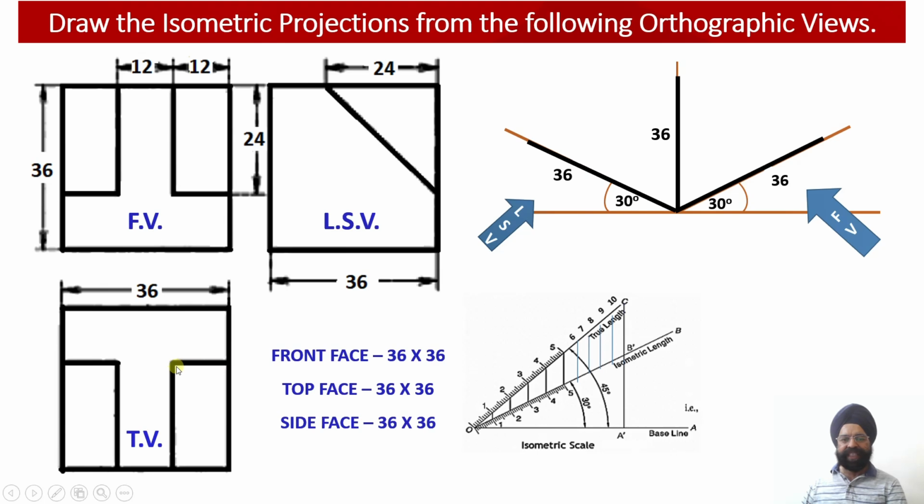And then once again at the center we have a flat web at the top face of the solid. This is the flat web at the top face. How do we say this is a flat web at the top face? Because this surface happens to be continuous. So this continuity of the surface indicates that this is a flat web which is lying at the top face of the solid. And then these are two inclined webs.